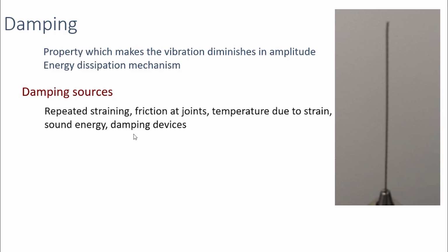And in concrete structures, because of repeated straining, there will be opening and closing of cracks. That will dissipate some amount of energy. And in some structures, there will be additional damping devices installed to absorb some energy during vibration. So, all these mechanisms will contribute to the energy dissipation in the structure.